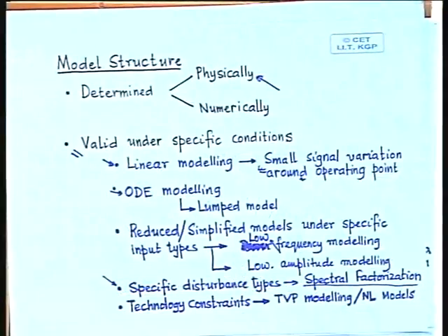For example, you have already done that in your Kalman filter, where you used an unmeasurable disturbance in your model. How do you know that the disturbance acts like that? It will be so only if certain mathematical conditions hold, for example, only when the power spectrum of the disturbance can be spectrally factorized.